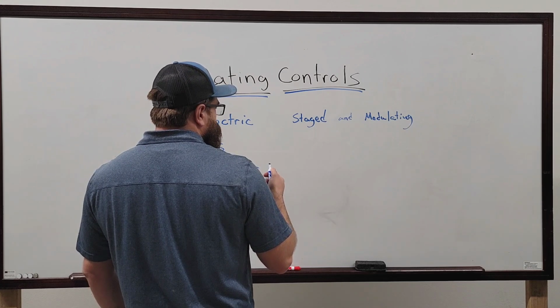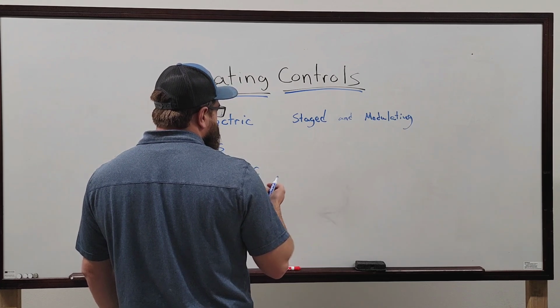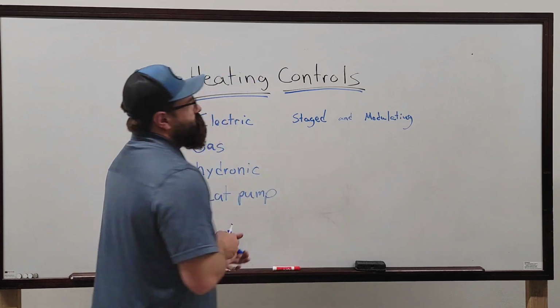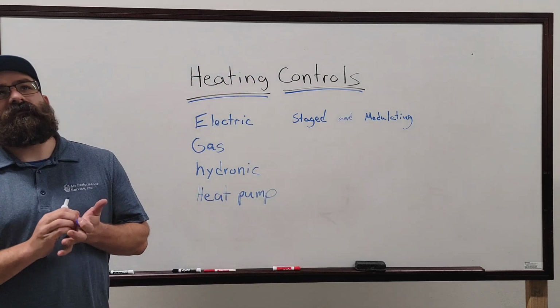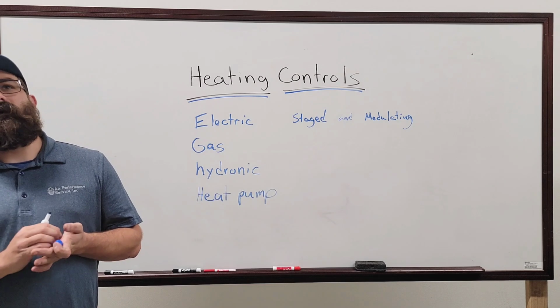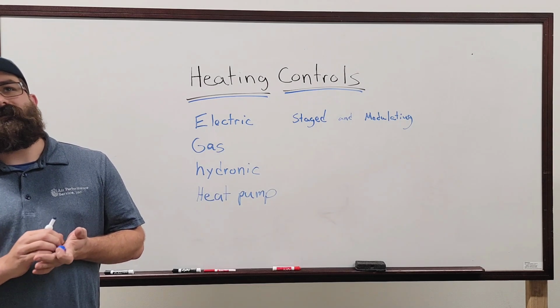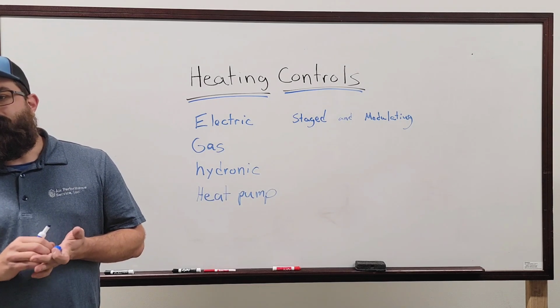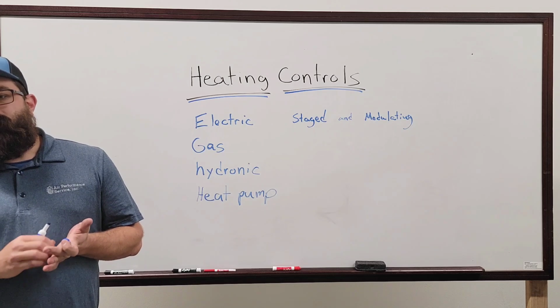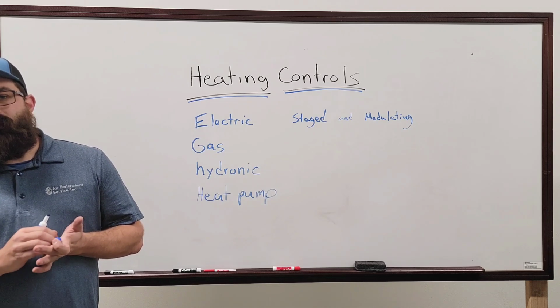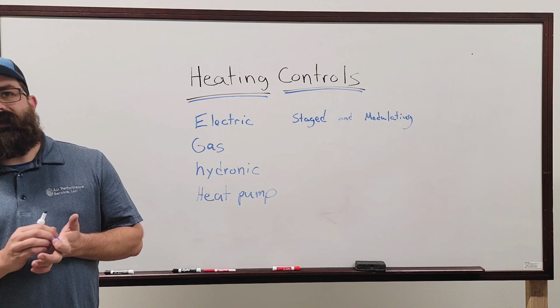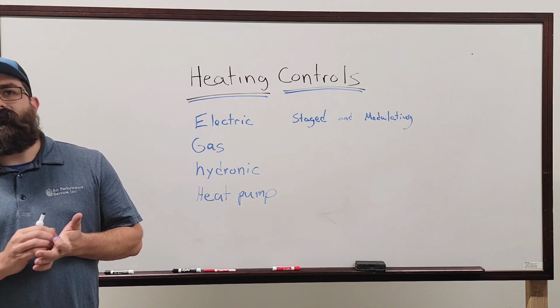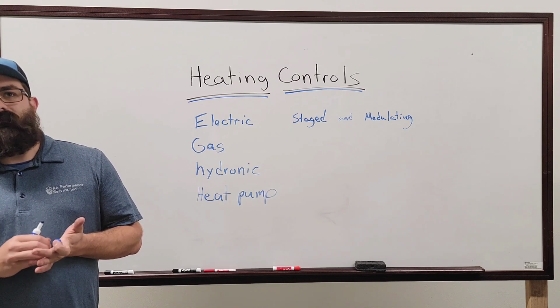It'd be the same thing for gas, wouldn't it? Yeah, that's what I'm thinking. I'm trying to think of any applications where we control a burner. Usually it's just a simple on off. Yeah, you're just firing the load. I'm trying to think if there's any that I send a 0 to 10 to, or even a 4 to 20.